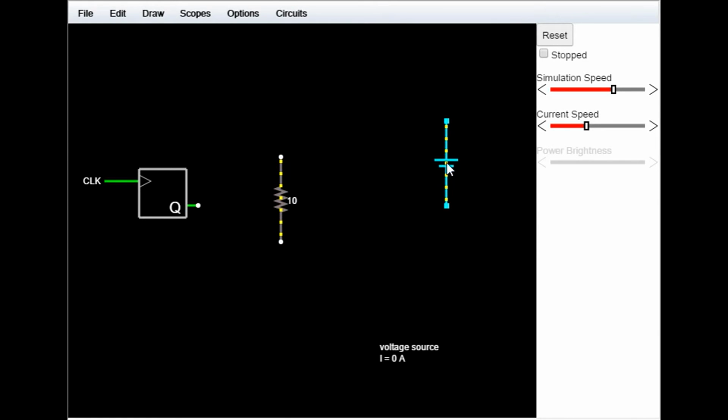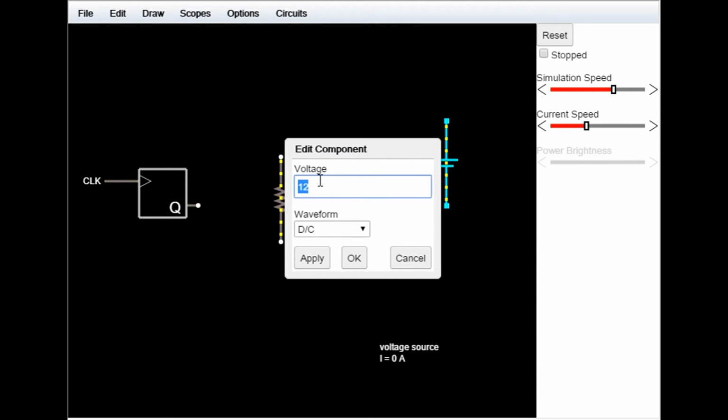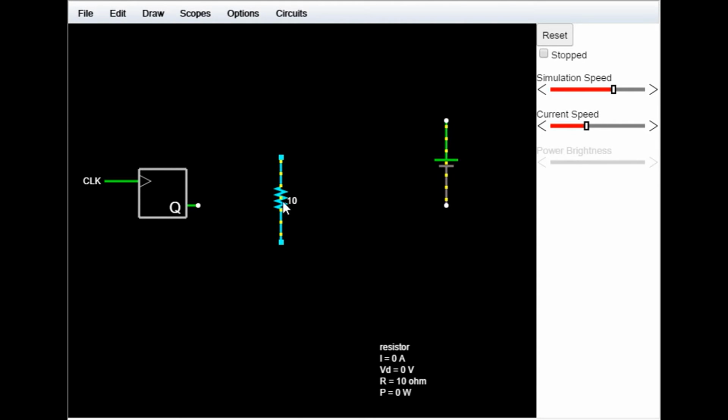And here we've got a battery, and I just made a 12-volt battery. So let's say we chose this motor for our project, and this is a 12-volt motor, which has a 10 ohm resistance to it. Okay. First thing you might do if you were trying to set up a circuit and you hadn't done anything like this before is try to drive your motor directly from your microcontroller. And as you can see, this seems to work.